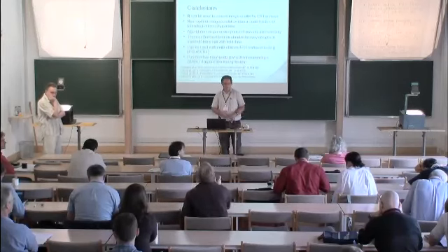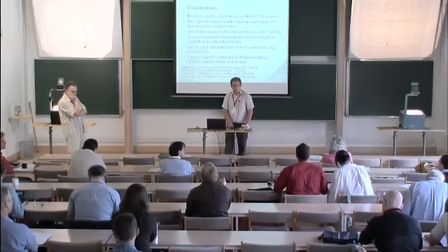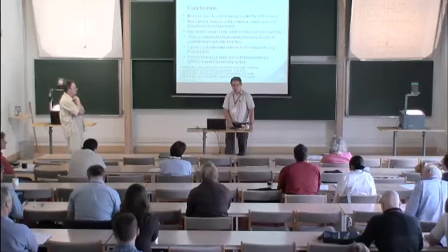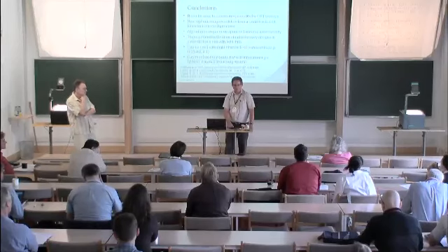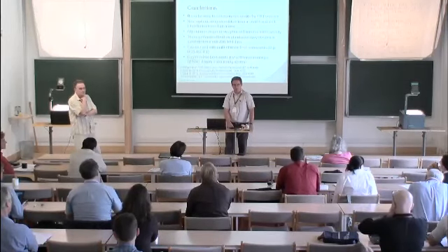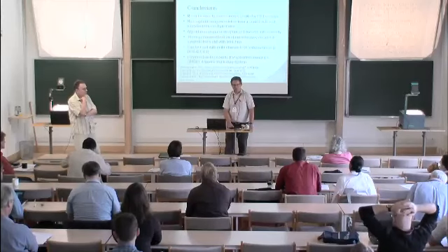I wonder if this polarization effect produces a bias in the measurement, right? Yeah. You could model that and subtract it and correct for it, couldn't you? It's difficult. It's very dependent on the ground conditions as to how much of a polarization effect you're going to have. So without a lot of prior knowledge at the particular survey site, you wouldn't necessarily know the magnitude of the effect, I think.